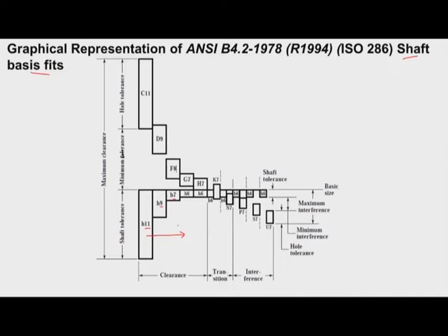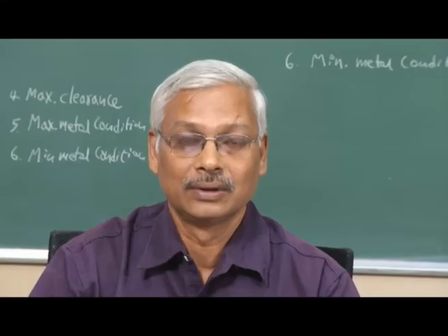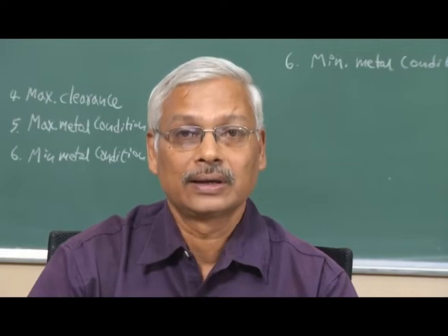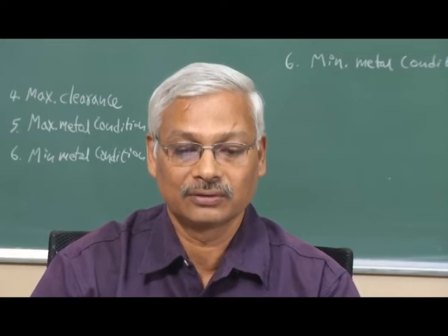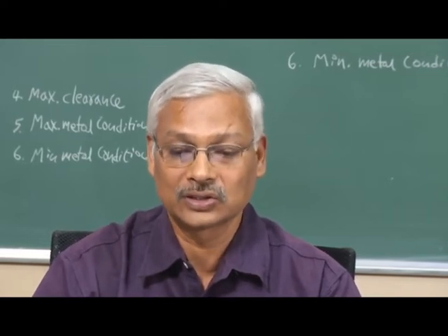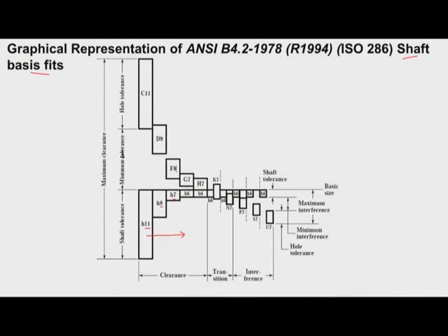to select the precision machine tools to control the sizes properly to provide the tight tolerances. So when the tolerance grade increases like IT 8, 9, 10 like that, the tolerance gets widened so that we can select not so precision machine tools, and the cost of production will decrease. Again, the selection of fit and tolerance depends upon the application that is needed. Similarly, we are varying the shaft sizes here, C, D, F, G, H.